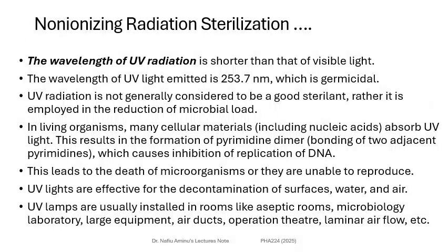Okay, so UV light is effective for the decontamination of surfaces, water, and air. As I have cited the example, I recently observed one of the pharmaceutical plants using UV lights as a supplementary sterilization method for their water system. So it is considered as one of the effective methods that can be utilized to get rid of microorganisms from the water, among other places.